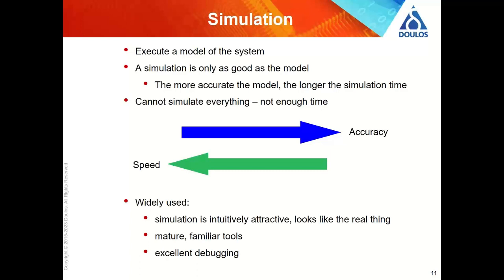The approach that's taken to modeling has varied over the years. So maybe back in the 1970s, the best you could do would be to run a SPICE simulation of transistors. But that takes forever. If you want to speed things up, maybe you can replace the transistor models with voltage-controlled switches. So that simplifies the work of the simulator. For a digital circuit, you can still get good accuracy, but that's still slow. So languages like VHDL and Verilog actually model the behavior of the code that you write by looking at when particular processes are going to be executed, when signals are changing, and so on.